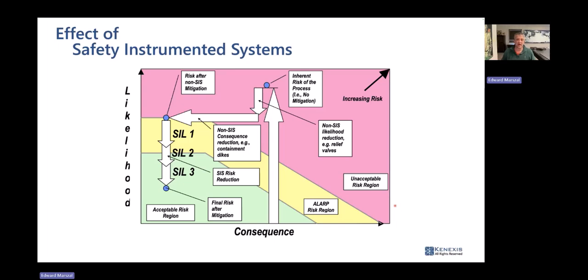But in a lot of the major petrochemical installations, your relief valve opening is going to send you into a flare header where the safety consequence is essentially going to go to 0, because your vent and disposal system is going to allow you to safely handle that discharge. You're going to send it to a flare header. You're going to knock out the liquids. You're going to burn all the gases that are coming off.